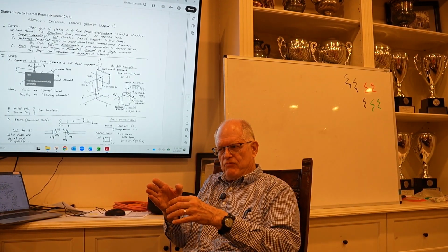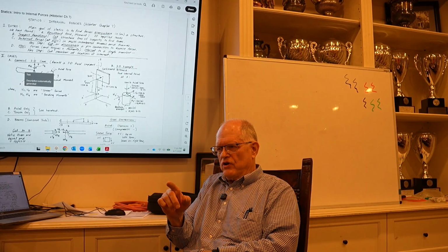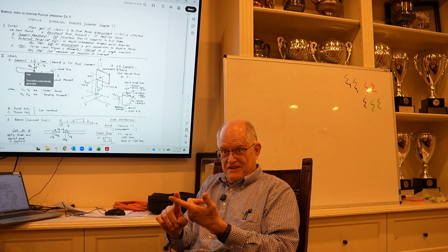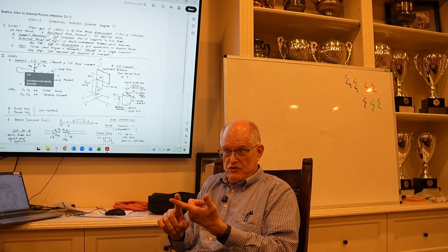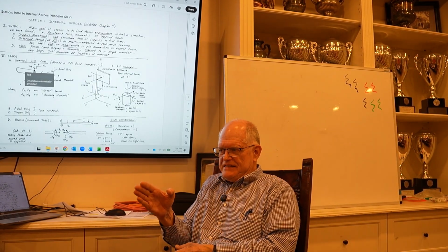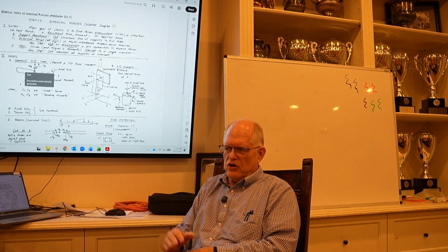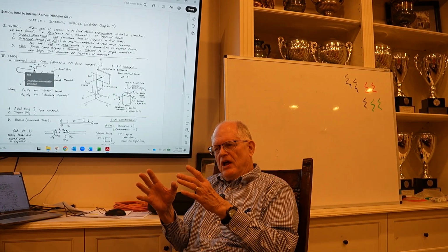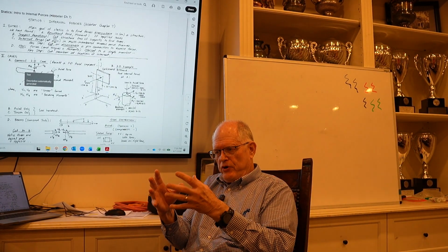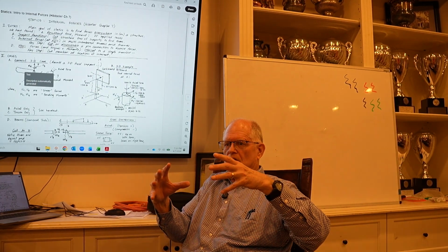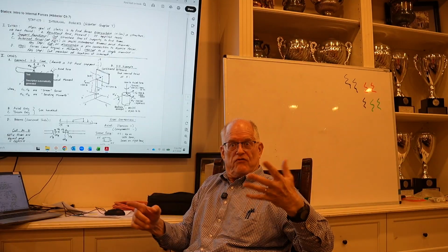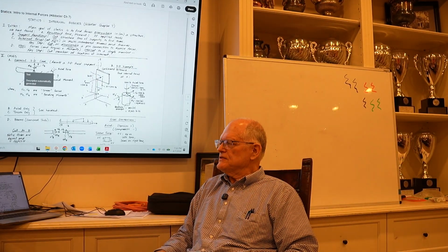So when you cut a member and you found that internal force and you said this is tension or compression, that was an internal force. Nobody told you that at the time, but you've already done a basic level of internal forces in looking at trusses. And when you cut that and applied the equations of equilibrium to either a particle, which is a joint, or a larger piece, which is a section, you were finding internal forces. So you already did that with trusses.